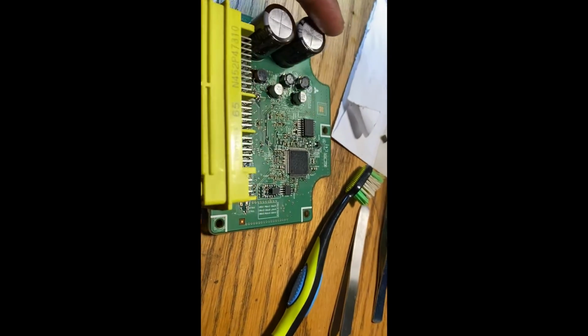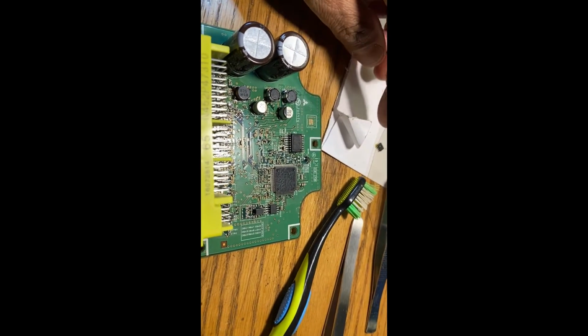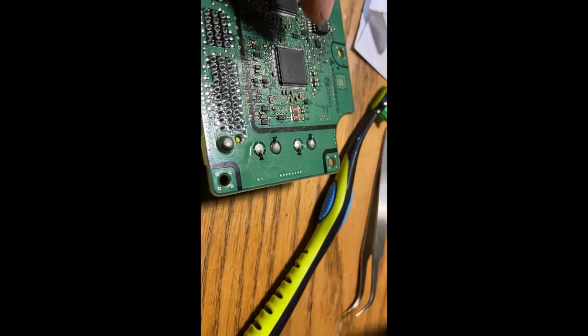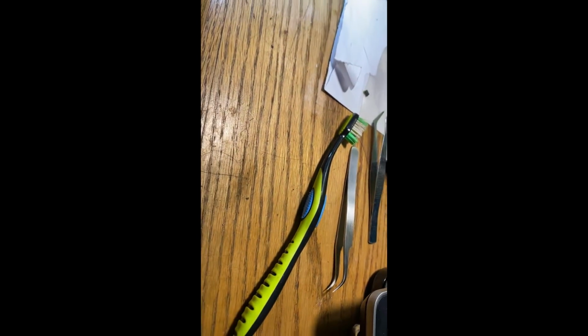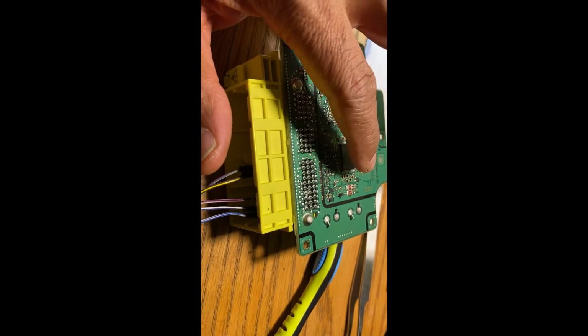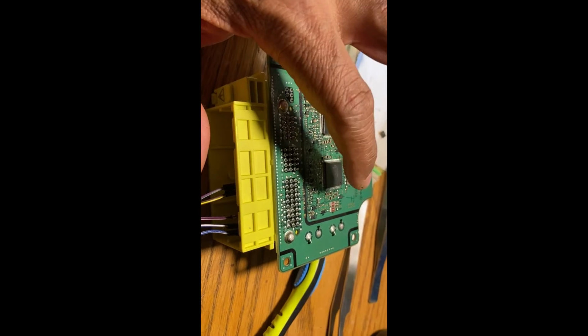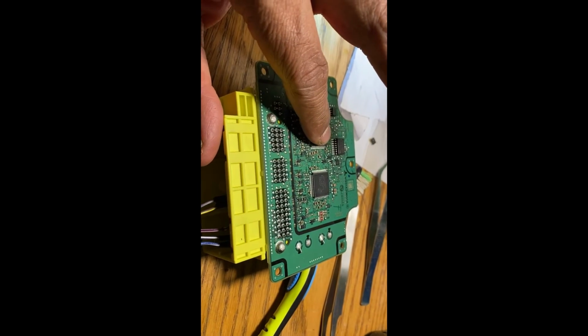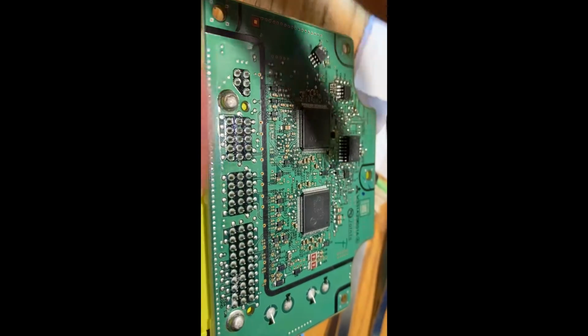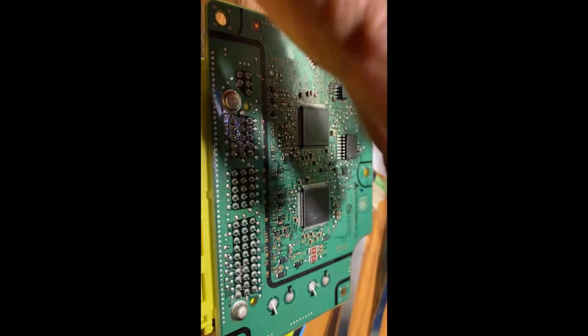Okay guys, so after replacing the chip, I put the old one back again, but I have no connection, surface mode failed. When I try to touch the processor, the Infineon processor on this side, it was extremely hot. If I had the thermal camera, you'd see it. It's very hot. I cannot even stand it. This one is okay, but this one is extremely hot. I cannot even touch it.